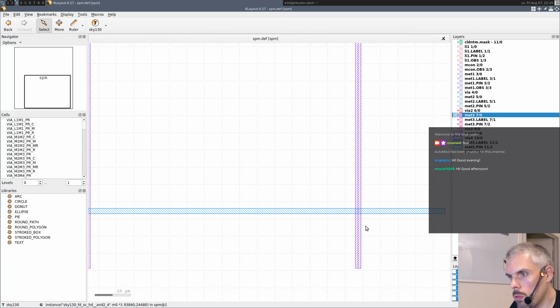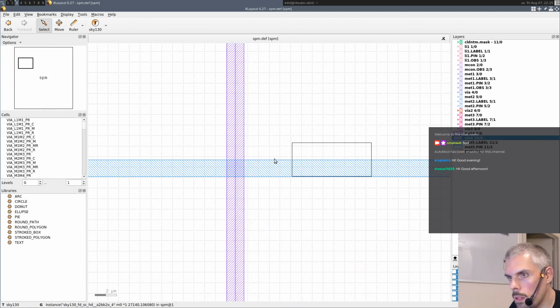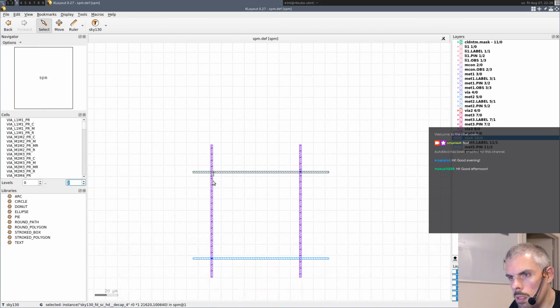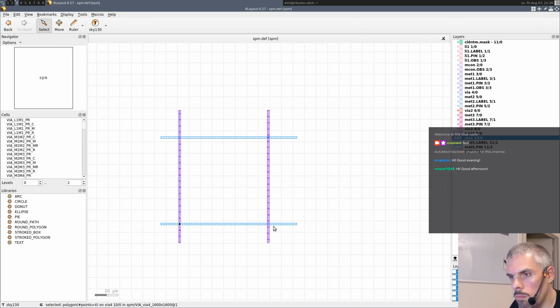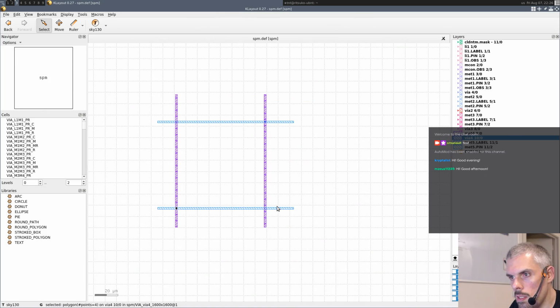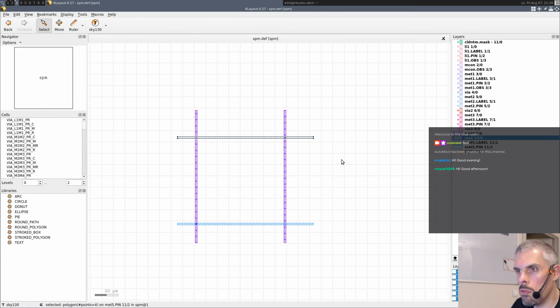And so you can actually see that, wait, there should be vias between them. Oh yeah, but you don't see them here. Yeah, here. So you see that this rail is connected to this rail through this via, because that's probably either GND or VCC, and then you have this rail which is connected to that rail. Again, we have this via. Here, of course, there are not many rails and not many interconnections because the design is super small, right?